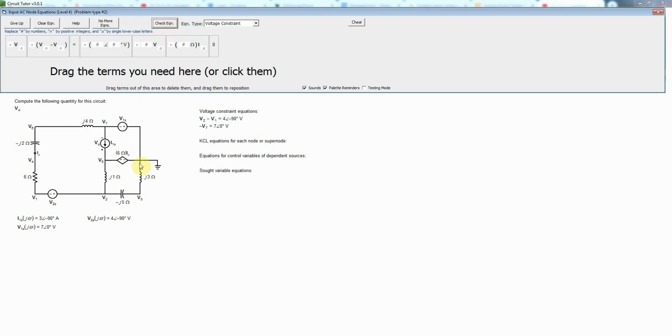And finally, we have the dependent voltage source. This is a current-controlled voltage source because the value of the voltage is what we call a transimpedance, in ohms, multiplying the value of this current Ix, which is this current actually over through this capacitor in a different part of the circuit. And that determines the actual voltage across this. So here, this voltage source is connected to ground on its minus side. So we will need